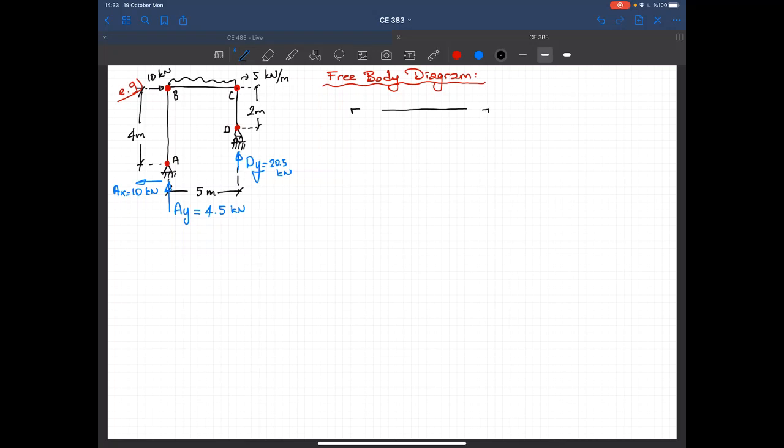So we are drawing the structure as composed of members and nodes, like that. Now here I'm showing a loading on this member. So for now, this is the member load for me according to my discretization. And I got 10 kilonewtons here. And this 10 kilonewton is a nodal load for me.